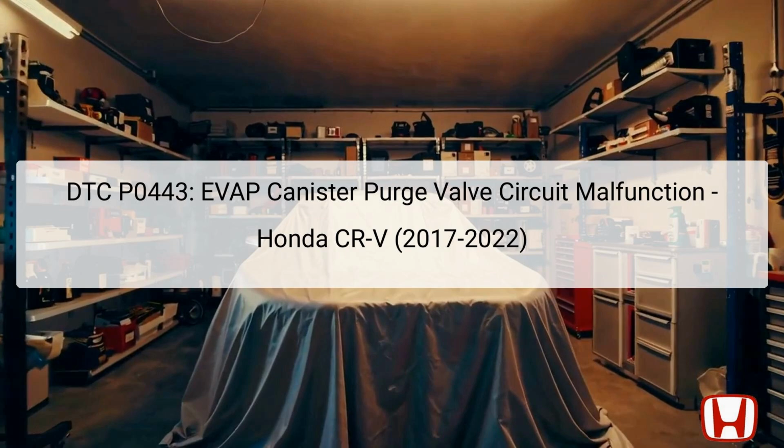Commonly located in the engine compartment, the EVAP Canister Purge valve is engaged once the vehicle reaches a certain operating state, allowing the engine to draw vapors when conditions are suitable. When this DTC is triggered, it indicates that there is an electrical issue or malfunction in the valve's operation, which can lead to insufficient fuel vapor management, causing performance issues or increased emissions.